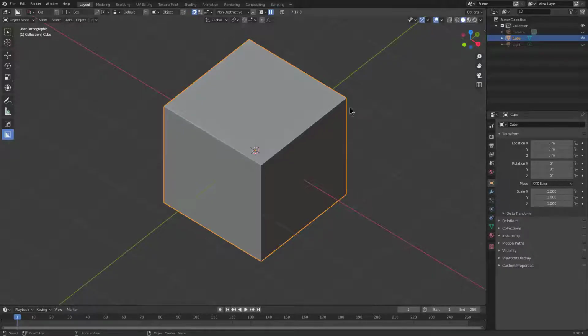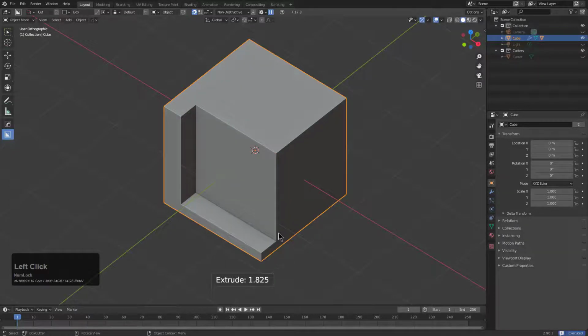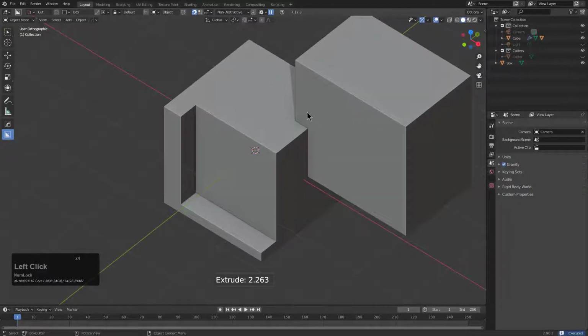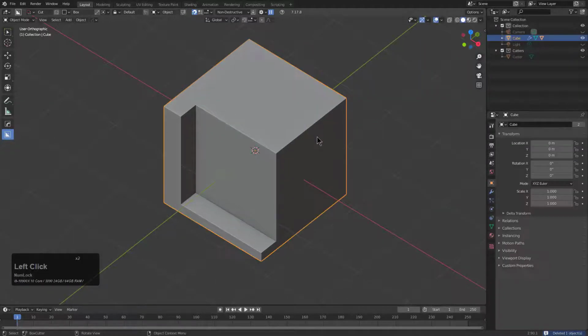So now that we're familiar a little bit with Boxcutter, we can actually go back and talk about the various types of modes. The whole time that we've been working, we've been in cut mode, which means that if I click and drag, I begin drawing a red box, which will attempt to cut into the shape that we have selected. Of course, always have the shape selected that you intend to cut, or else you will do what's called a make box, which is a box that is drawn whenever nothing is selected and is an entirely different type of system unto itself.